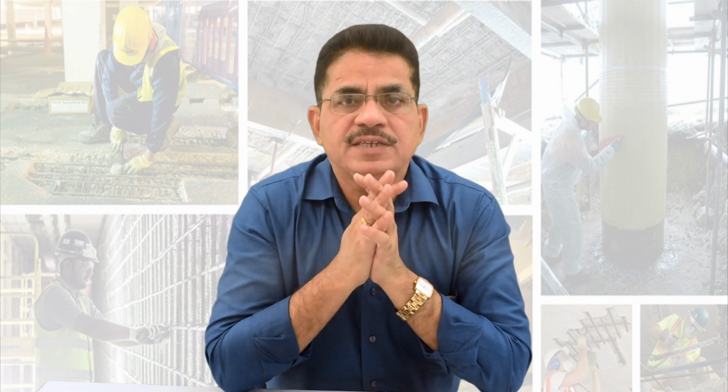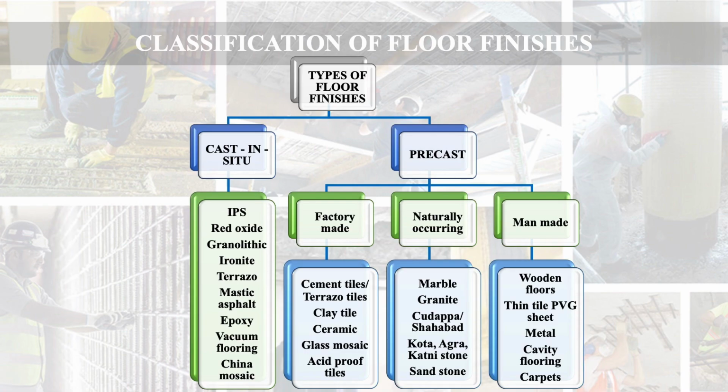Now let's discuss the classification of floor finishes. All types of floor finishes can be broadly classified into two categories: one is cast in situ and the second is precast. In cast in situ, the different types of floors are Indian patent stone flooring, generally called IPS, then red oxide flooring, granolithic flooring, ironite flooring, terrazzo flooring, mastic asphalt flooring, epoxy flooring, vacuum flooring, and the last one is China mosaic flooring.